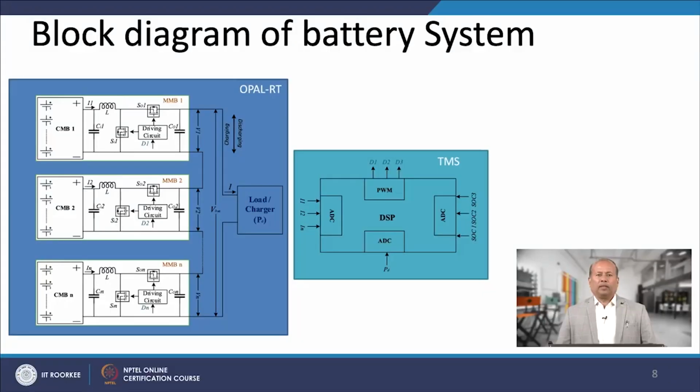3 battery currents are compared with reference currents generated from the algorithm. The SOC balancing algorithm is developed based on the average standard deviations. By comparing the SOC values with the mean values, a balancing factor is determined for all the 3 batteries in a similar way. Using the balancing factor, the power is shared among the battery modules accordingly. By using a PI controller, the voltage bus is maintained and PWM signals are also developed.